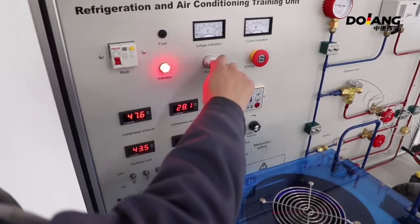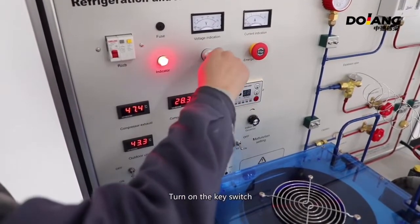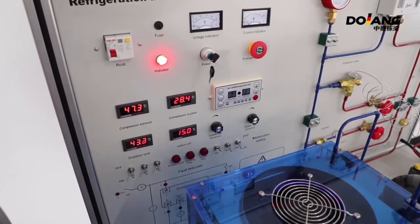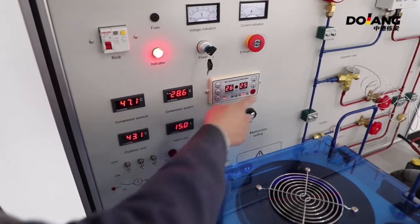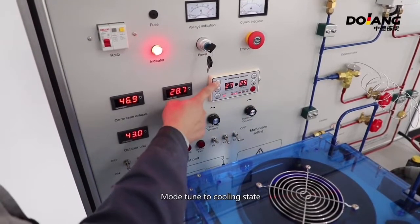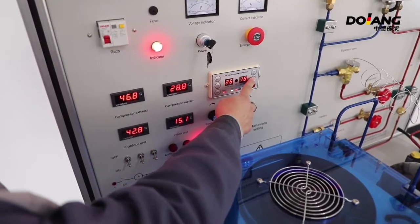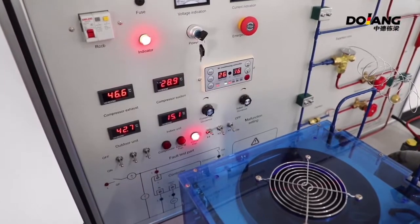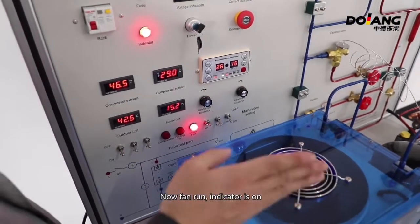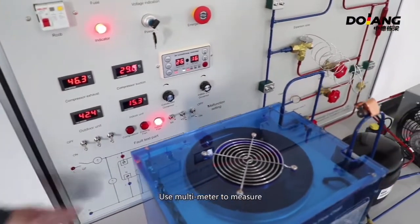Now do the fourth fault experiment. Turn on the circuit breaker. Turn K4 to off. Turn on the key switch. Turn on the controller. Turn the mode to cooling state. Now turn the temperature to the lowest. Now the fan runs and the indicator is on, but the compressor doesn't start.